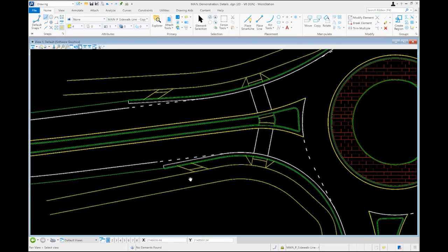We finished detailing out a few other elements as well in terms of detectable warning surfaces at the top of the ramp to delineate the edge of the roadway space from the pedestrian space, as well as making sure that we've got our curb ramps or ADA curb ramps at each end of the crosswalk with our detectable warning surfaces at the bottom of the ramp along the delineation of the roadway, and detectable warning surfaces along each side of the splitter island as we discussed previously.